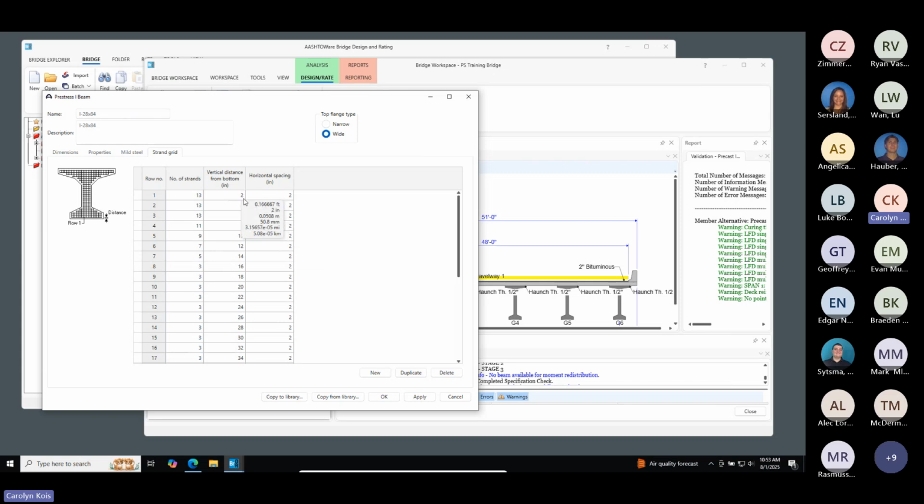So what we did is add a second potential strand row location at approximately that same height. Sorry, this is showing all these things when I hover over it. Let's say we have this row of strands that's 6 inches from the bottom, and we wanted to do that type of bundled strands. For that template, we added an additional possible strand position that's just 0.1 inches off as a vertical distance.